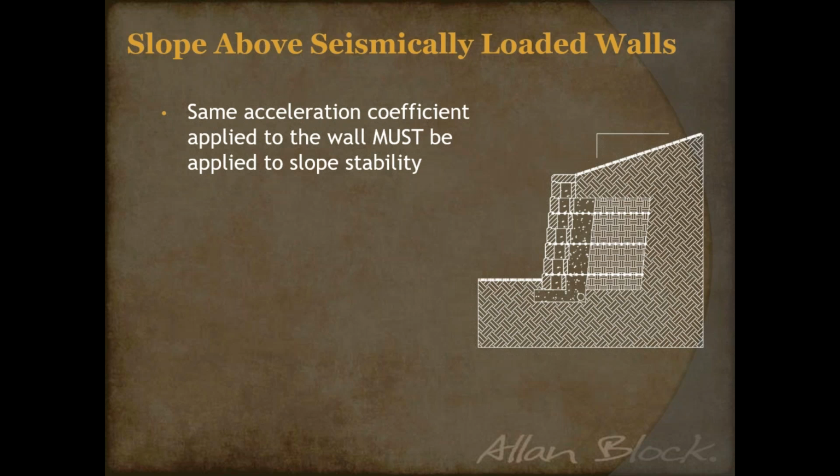But then you stack this massive slope above the wall that's never going to be stable in a dynamic event. And so when the earthquake hits, now the slope fails and the retaining wall is just going for a ride. To us, we've always looked at these retaining walls less as walls and more as reinforced slopes, because that's really what they are. They're just almost straight up and down because of that block providing that structural form to backfill and compact as you go through this.